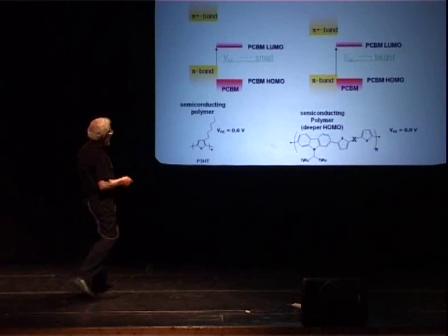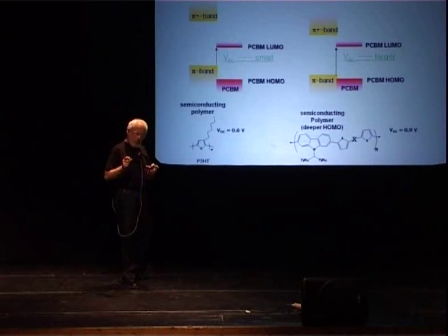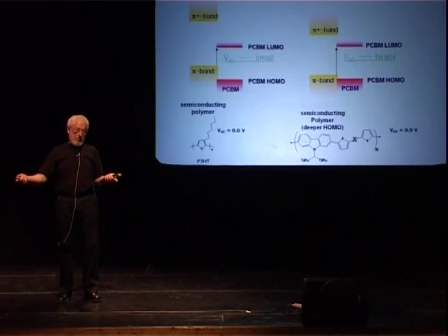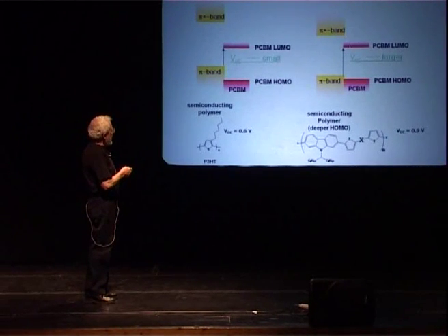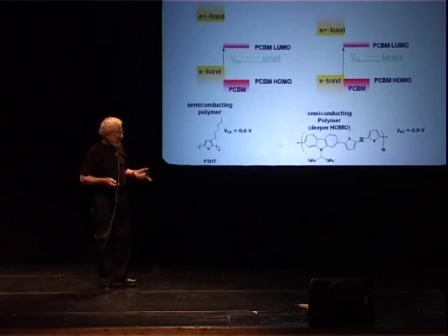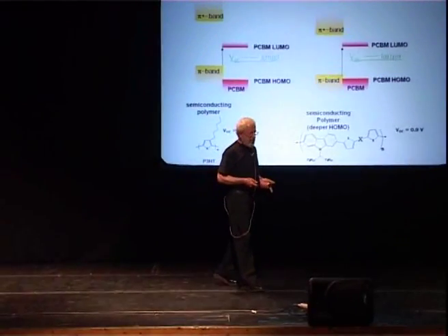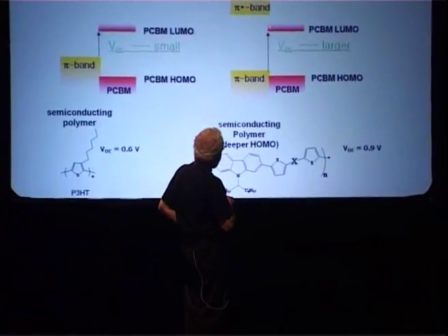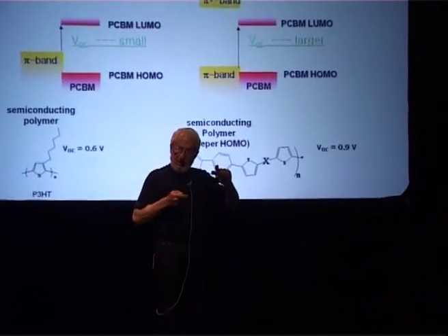The goal would be to have the energy gap here approximately maybe a little bit bigger than silicon, because then I absorb most of the photons in the solar spectrum, and have just enough band offset to assure charge transfer. That's been a controversial area. Many people have expressed some doubt that one can have both of those, that is, to have a small gap and still get electron transfer.